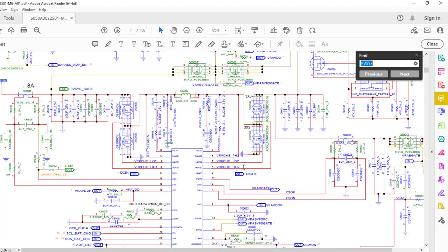converter. So you know how the buck boost converter works. If you don't know how a buck boost converter works, then you can watch our buck boost converter video, how the things work in buck boost. A buck converter is basically reducing the voltage, and a boost converter means boosting the voltage. So this circuit reduces the voltage, and simultaneously can increase the voltage. If the power is coming from this side, okay, then it's a buck converter, and if the power is coming from this side, then it's a boost converter.